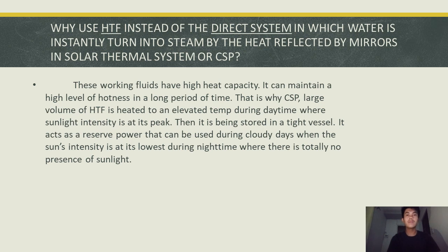A fluid's ability to withstand thermal cracking, or thermal degradation, is the primary factor in setting its maximum bulk fluid operating temperature. This temperature is the maximum the fluid manufacturer recommends, at which the fluid can be used and still maintain an acceptable rate of degradation over time.